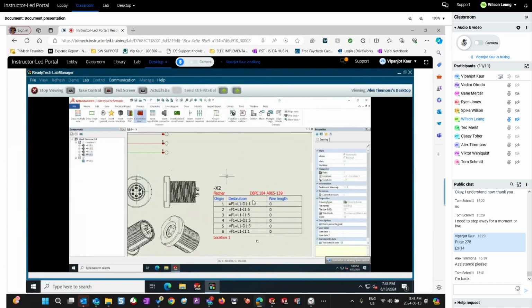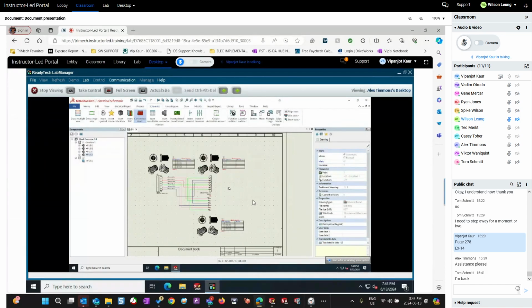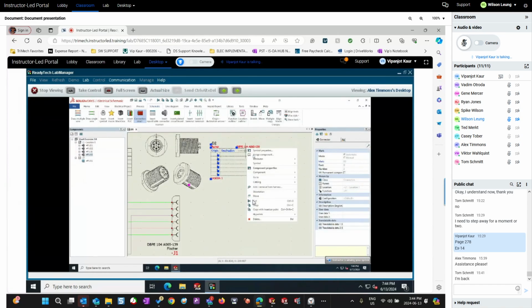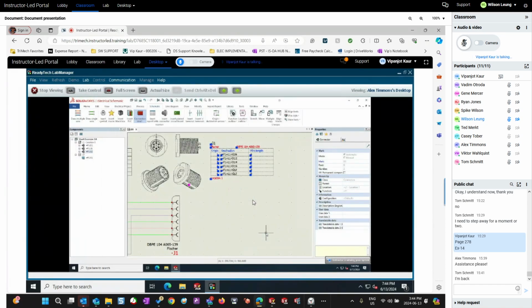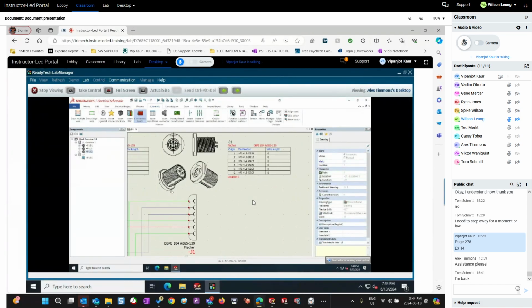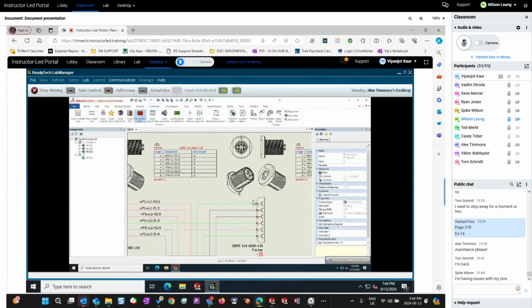So right on the top of the page, there is another table, a connection label symbol. Can you link that to the first connector, please? Right click, symbol properties. You're linking it with J1. Very good. Hit OK. The table populates for you all the pin data. Which pin from J1 is going where? What destination component? So then you would say, VIP, how did you add this connection label symbol?